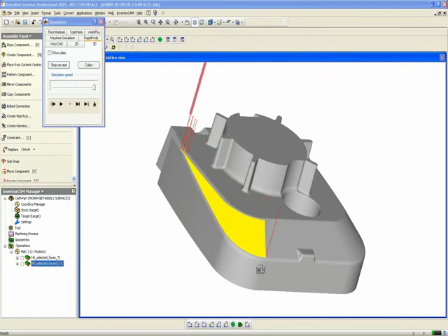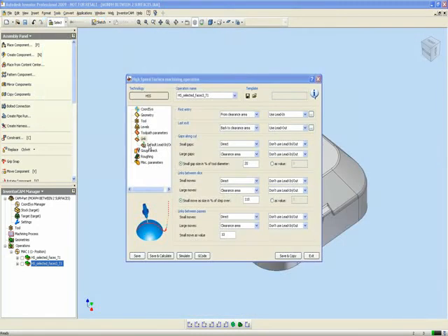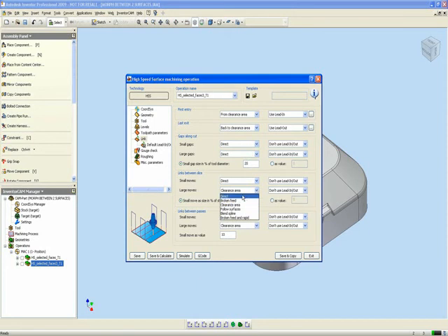The way to control this is we can go back into our leads area. Now if I go back and open my link area over here, as you see, we'll make some changes. First of all, gaps along cuts, there aren't any, but just to make sure we'll have direct. Now I'll change my link between slices to have direct. In other words, to go directly to the next area instead of jumping up to my clearance level. I'll do save and calculate.